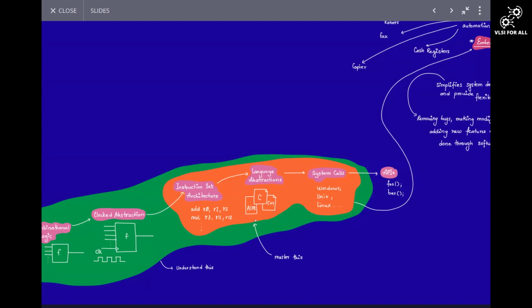So, in one of my projects at one of my previous companies, Silicon Labs, we had an embedded application wherein we sense the temperature, as I was just explaining. We need to sense the temperature on one task and switch to another task. This other task's entire job is to connect to the Wi-Fi and to connect to the cloud over a protocol called MQTT and send this temperature data to the cloud. Again, after doing this, it should switch back to the sensor task, send some temperature again, then switch to the MQTT task and send it over the cloud. So in these use cases, you may need TCP/IP to understand.